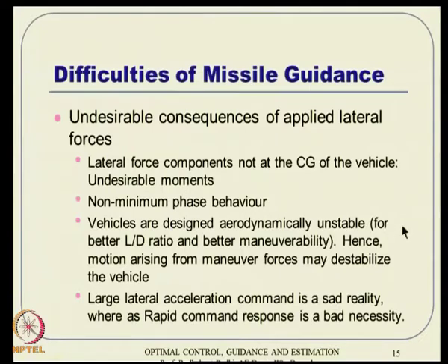And then the vehicles are also designed aerodynamically unstable. They are not designed stable, by the way, because they are designed unstable to have a better L/D ratio, lift over drag ratio, and better maneuverability also, because lift will be high. Hence, the motion arising from the maneuver forces may destabilize the vehicle also. That means, if you don't do a very careful exercise, the vehicle is inherently unstable. So, if you excite it a little more, it will go to rotational instability very quickly.